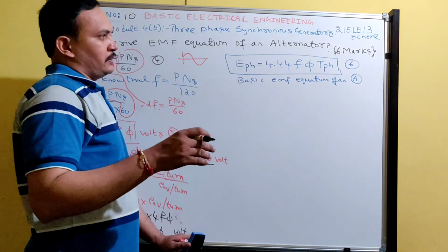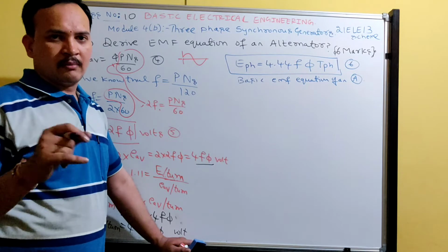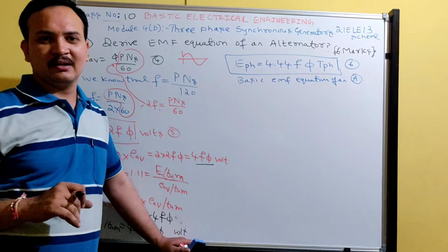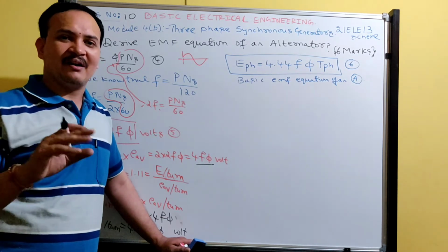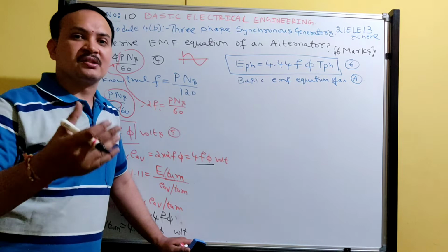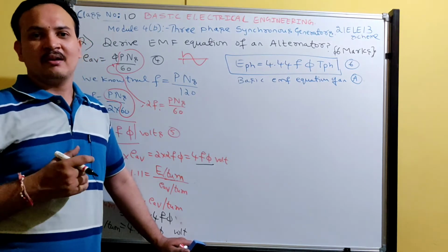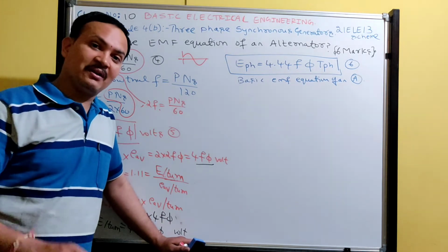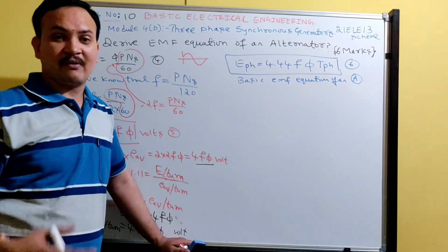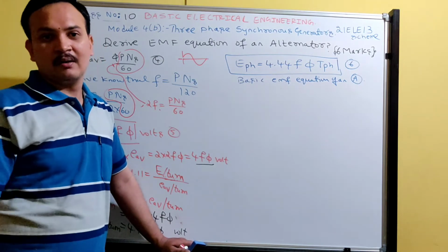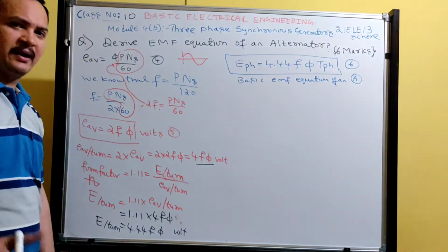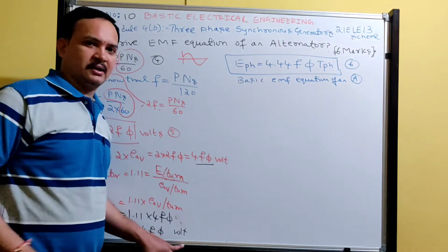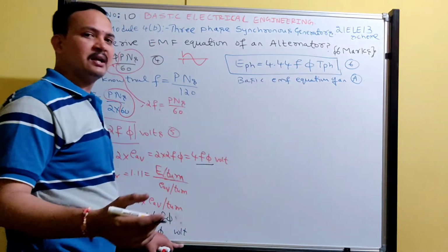The alternator will have windings. The armature winding may be lap connected or wave connected, single layer or double layer, concentrated or distributed, simplex or duplex, progressive or retrogressive, fractional slot or not fractional. Winding is a separate subject. If I consider winding factors, then the EMF equation slightly modifies.